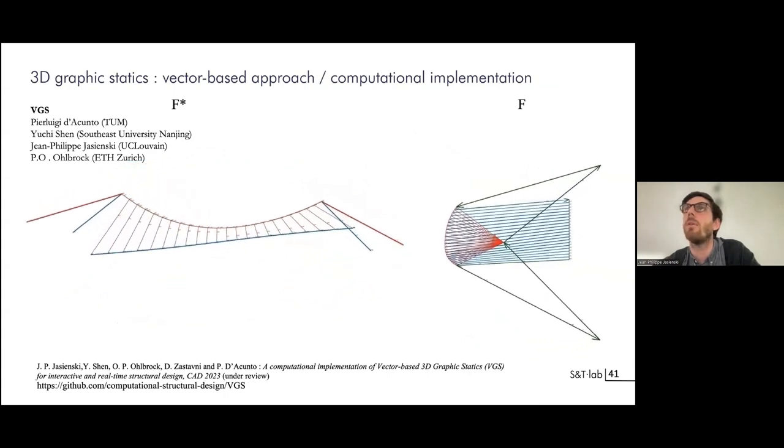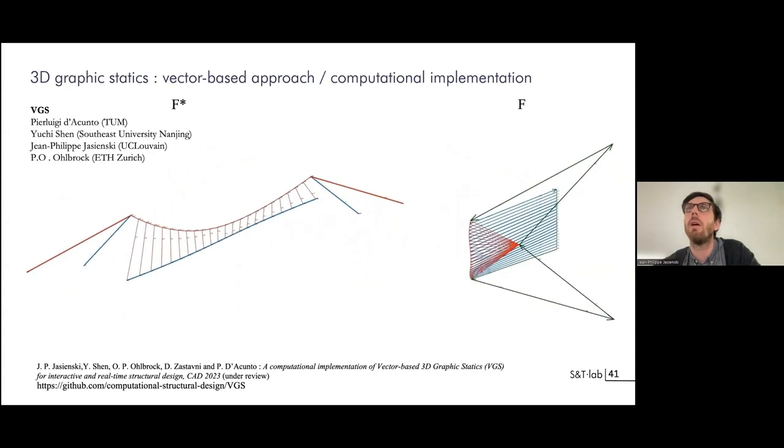On the right, the force diagram, okay, of a bridge with a compression deck and two compression pylons. And here it's the force diagram, and so you can very easily read the force in all the deck members here on the right, okay, corresponding to that. One pylon, the other pylon, corresponding to the four external forces that are doing like 1, 2, 3, 4, and that they close with the small red forces corresponding to the angles.